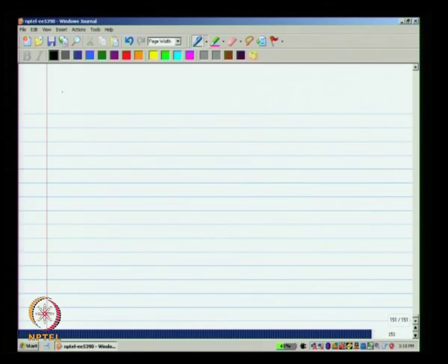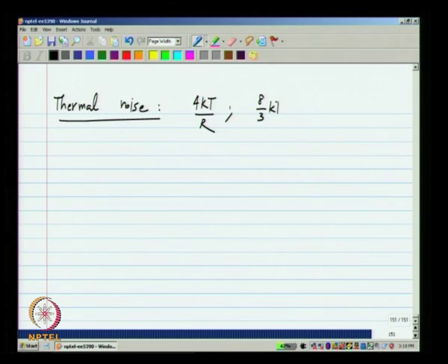Okay. It is very important to know the systematic way of reducing noise. Now, we have looked at thermal noise in resistors and MOSFETs. The thermal noise current spectral density is 4kT/R in a resistor and (8/3)kT gm in a MOS transistor. Okay. Now, the point is, both of them are proportional to the absolute temperature T. So, another way of reducing noise could be to reduce the temperature.